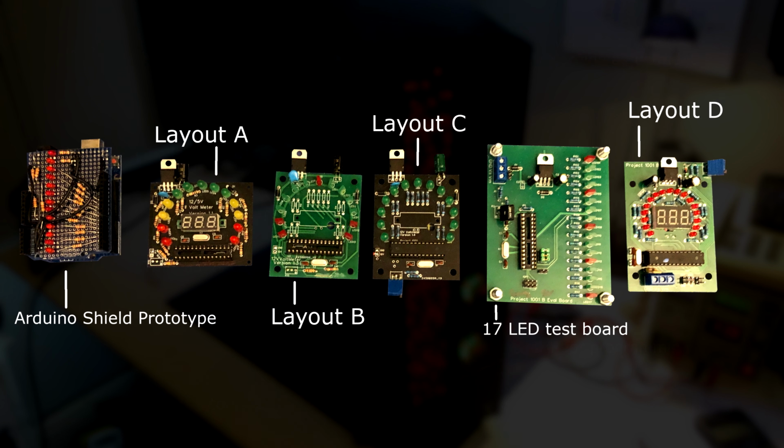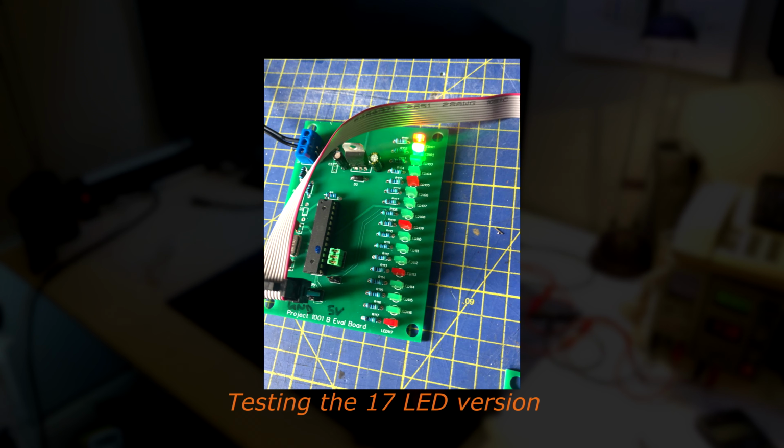The board went through several revisions, so I decided exactly what it was I wanted, dimensions, electrically. I started constructing with a crude Arduino shield to test my code, and then afterwards I started schematics and layout in EasyEDA. I went from 13 LEDs to 17 LEDs, and I also placed an Arduino ISP by the end of the development process.